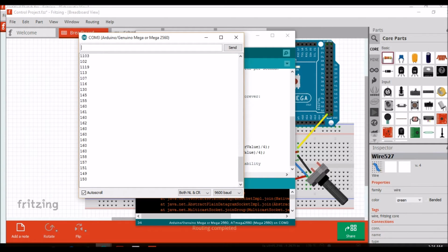The push button is not pressed yet, it's just sending a 3-digit value. As the push button is released, the push button data is 0, and the data is 0 times 1000 plus 162, so the actual data is 162.